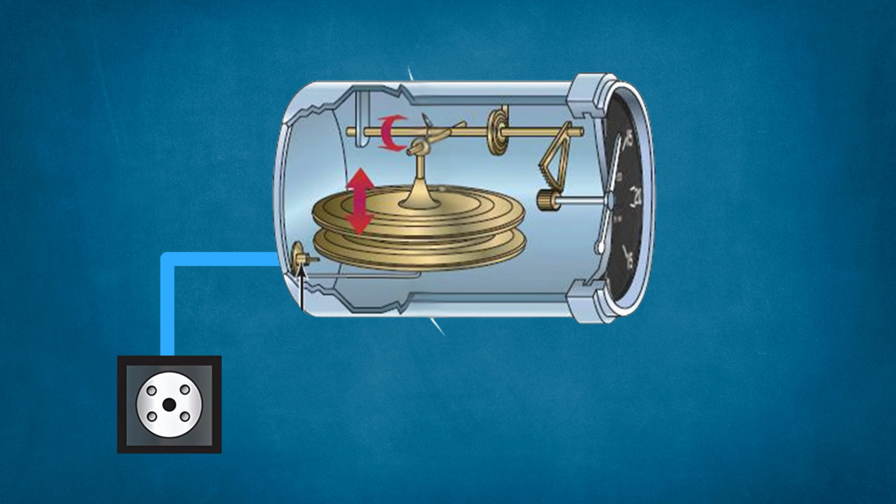When the aircraft climbs or descends, the static pressure will change instantly in the unrestricted opening, but the case pressure will take longer to adjust because of the restricted opening. This creates differential pressure acting on the diaphragm, which then moves and rotates the connected needle too. The faster the rate of climb or descent, the greater the differential pressure, and the more the needle will swing.